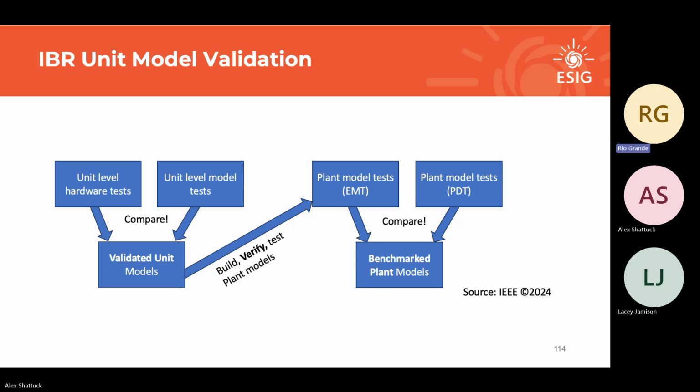So it's not exhaustive. I think more type tests are always good because at the manufacturer level, they're doing 1,000 of these tests, and we're asking, I don't know, remember what it was, like 20 or 30 tests in the IEEE. So that's the small subset list, and that's a good place to start. And that's things like fault ride-throughs and different fault levels and some control schemes and ride-through modes and that kind of stuff. So for all intents and purposes, it should cover what you're going to do from that side. So that's a good place to start. And again, that's published probably in spring, January, February.